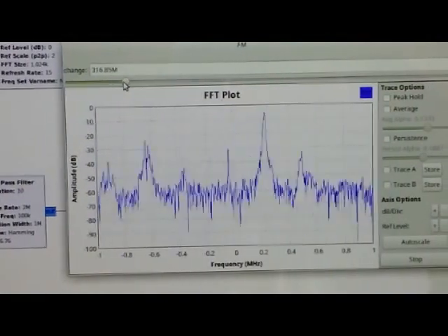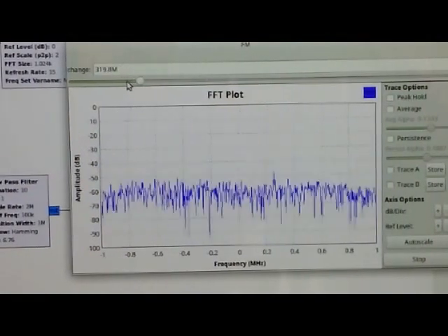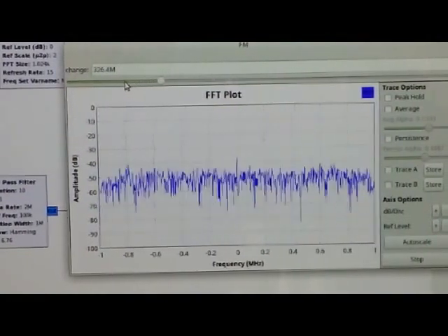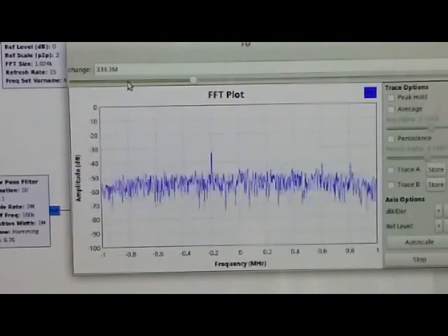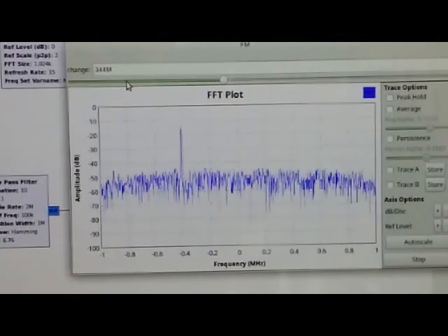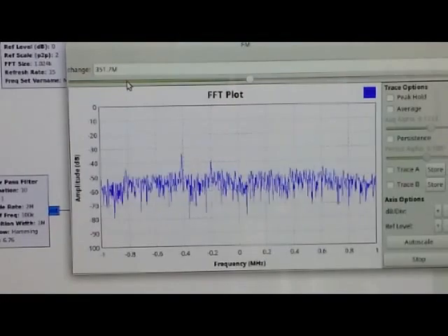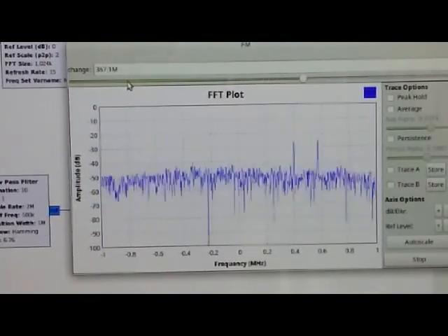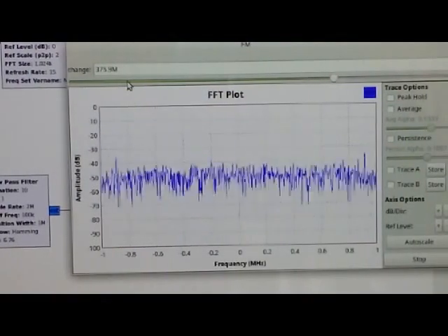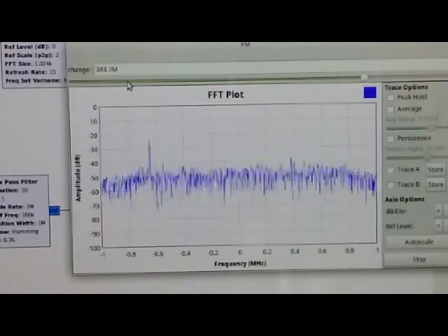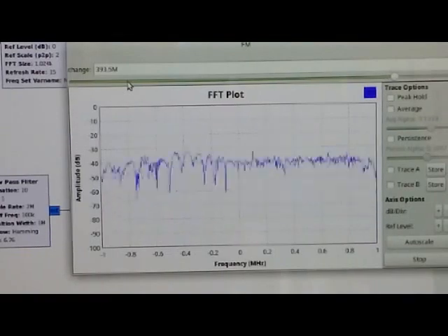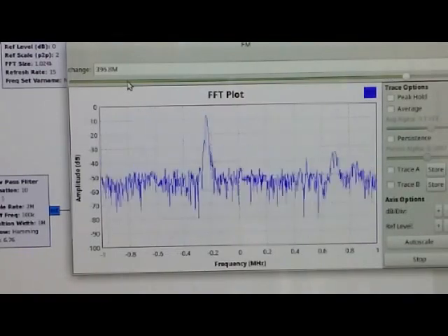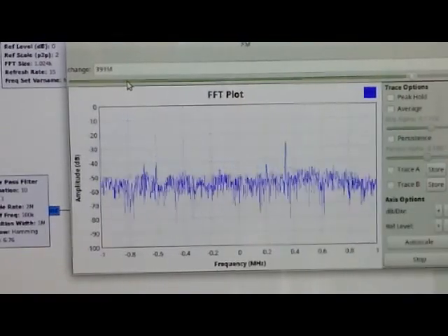One thing I'm noticing, and again I was checking this out before doing the video, and I'll just show you here that I'm picking up harmonics every 80 megahertz. And we should have our next one right around 400. Yep, you can hear that's 396.